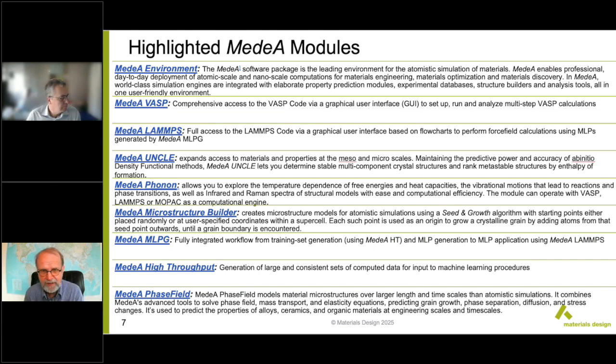So you generate a potential and try it out to see if it's not properly representing certain configurations. So you add them to the training set and refine the potential. So that's more of a process where you are involved more explicitly. So again, MLFF in VASP for specific systems as a turbocharger for specific molecular dynamics simulations on systems that you can handle with VASP, and MLPG training a potential that is generic and can then be used for very large systems, like 100,000 atoms if you want. I hope that this answers the question.